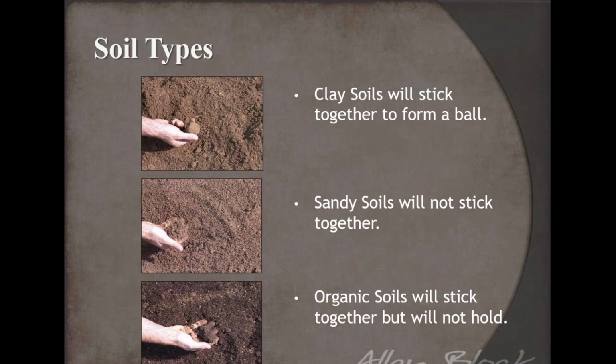And then if I grab that sample of soil and it's maybe a little bit more dark in nature, black in color, and it will stick together but really not hold, it doesn't really have any stability properties, we're probably talking about organic material.